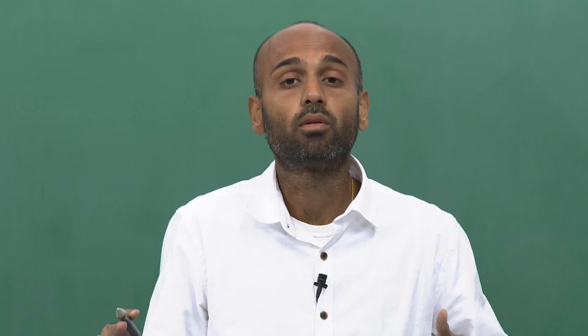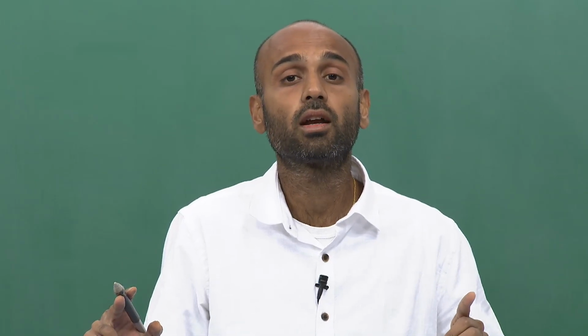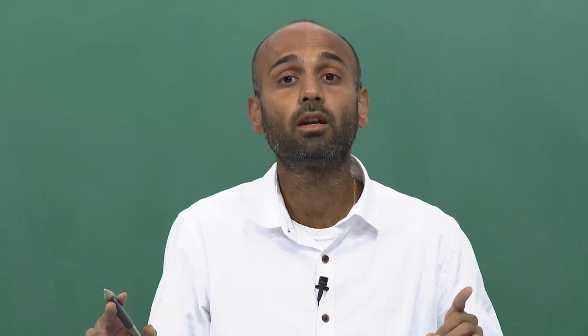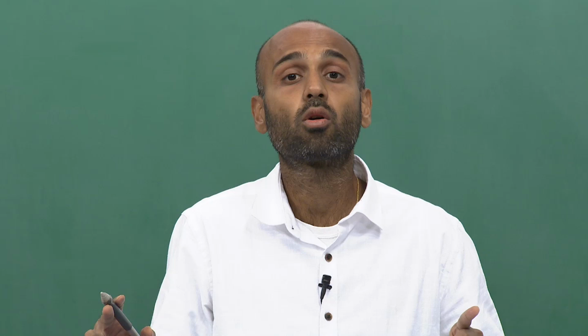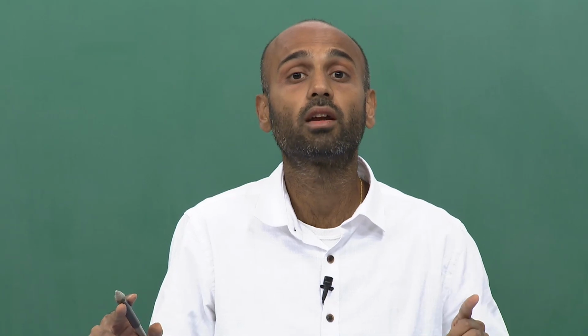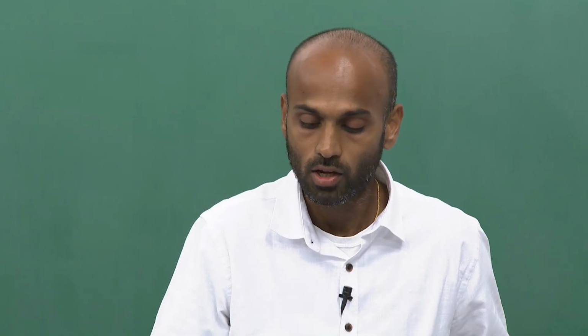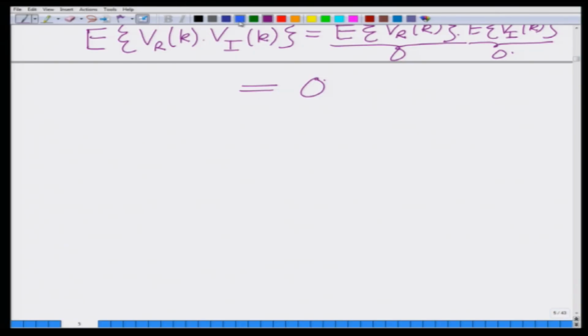Such a noise, so both real and imaginary components are identical, Gaussian, and both the real and imaginary parts are independent. Such a noise is known as a complex Gaussian noise. Further, it is a zero mean symmetric complex Gaussian noise. So, let me elaborate on that fact a little bit more. Vk is known as the zero mean symmetric complex Gaussian noise, and this is the most important frequent assumption, which stands for zero mean